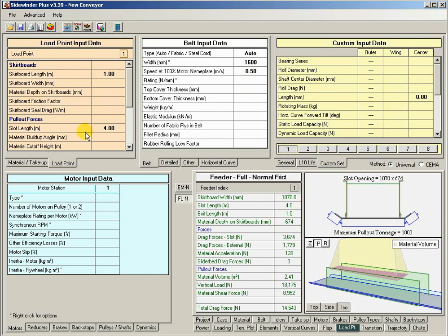And as I discussed in the previous tutorial on load points, there's really 2 different calculation methods. One method calculates this yellow volume based off of a 75-degree buildup angle here. This material buildup angle, that's just the default. Now you can also change that to whatever you want.